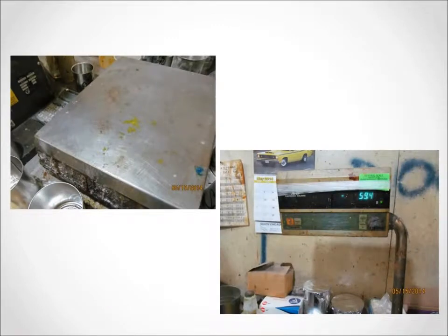Being a small-scale production, any pigment or other additive would be weighed out on a scale and manually mixed together with the MOCA. The exposure potential to the melted MOCA or isocyanate used during mixing is extremely high, and special care should be taken to reduce and eliminate any splashing or spilling that could occur during mixing. As seen here, splashes can be seen on virtually every part of the scale. While the contamination consists mostly of various pigments, special care should be taken while handling any chemical in order to reduce the potential for skin exposure, prevent the spread of contamination, and to keep the work area clean in general.